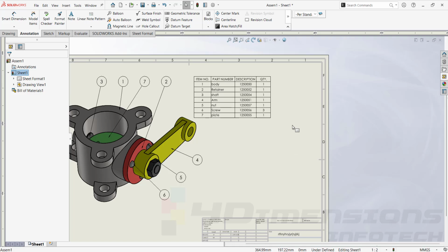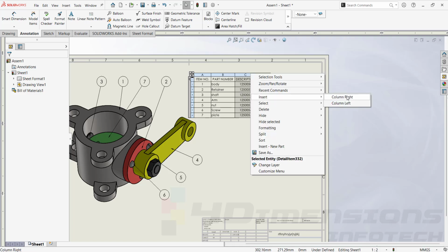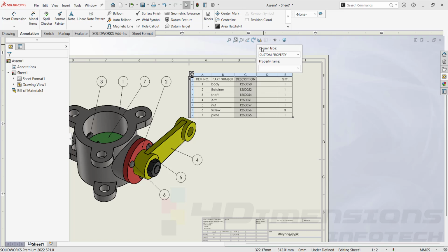So to call the other properties, when you drag on this table, you can see the blue color strip here and one black arrow appearing, showing the direction on the downward side. You just need to right click on this blue strip and you can say insert column to right and left for the property. At which position you want, you can go for that. I'll say on the right side. As soon as you click on this direction, this property box will appear here.